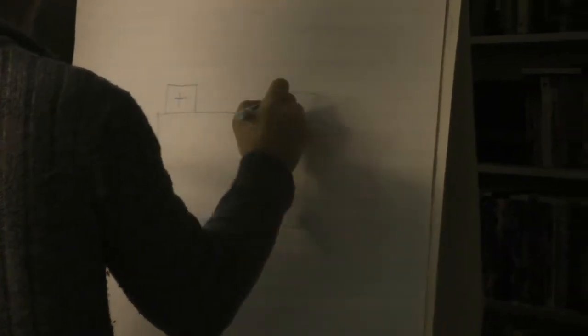So if we have a battery here, and we label one positive and one negative. We remember current flow leaves the positive and returns to the negative. Electron flow does the opposite. So the cathode in electron flow is where it leaves, which means this is the anode. Then we have some part, and we'll just drop in a diode to show what's going on here. It will then enter into that side. This side becomes the cathode side of the part, because that's where the current comes into it. And the anode is the other side of the part, because that's where the current flow leaves.